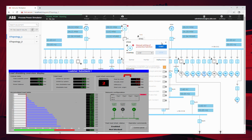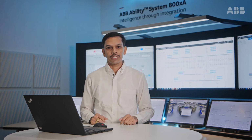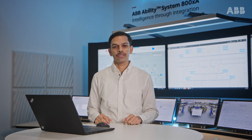Once the load shedding is triggered, the transient window will pop up where it records the transients of the network, voltage and frequency. You can see a dip in voltage and frequency, corrected back by the other two generators working in the network to the system voltage. With all relevant information at your fingertips, it's easy to tune protection settings, generator parameters and load shedding priorities.